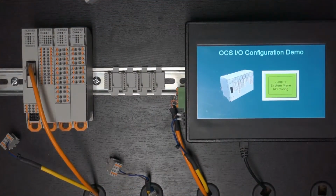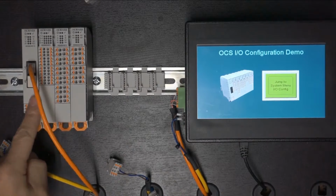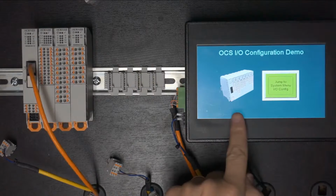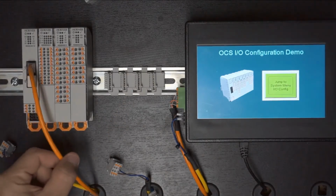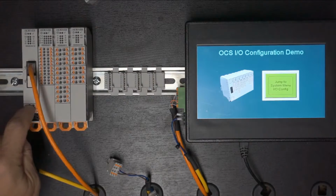Okay, here's our first bench setup. I have an OCS-I rack that I physically assembled here. I have it connected electrically to my OCS through a CAN cable here. It's actually a modified patch cable like I've shown before. All right, I have a terminating resistor installed on the second RJ port here on the OCS-I base, and the OCS-I base is not powered up yet.